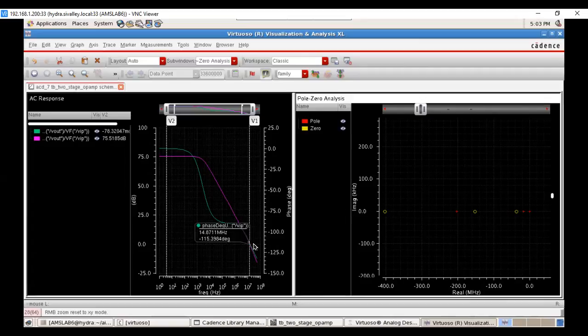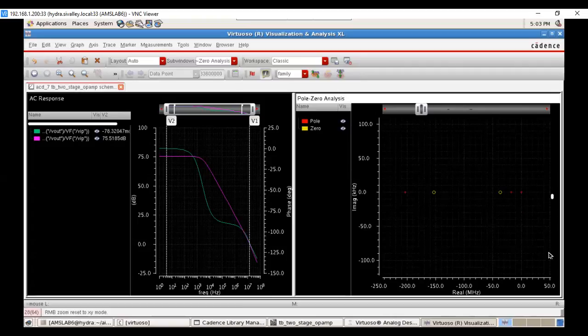But the poles and zeros that are dominant to this particular spec, you need to take at least 5 times. 5 times means if I design 10 megahertz, it will be 50 megahertz. Generally, it's a 5 to 10 range that we consider. It depends on the designer, and on what the application is. But in a very general, crude way, it's 5 to 10 times your unity gain bandwidth we have to take. Here I designed for 10 megahertz, so generally I will take 50 megahertz as a threshold for considering the number of poles and zeros.